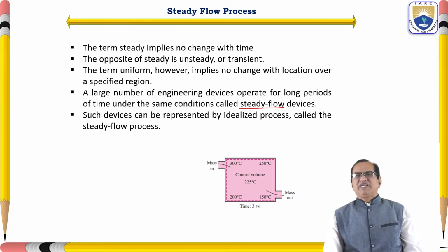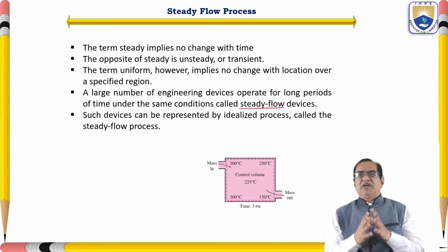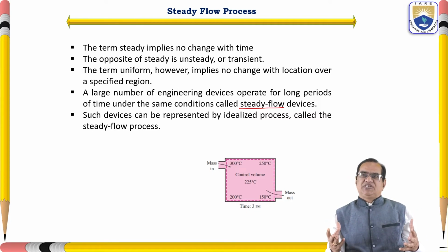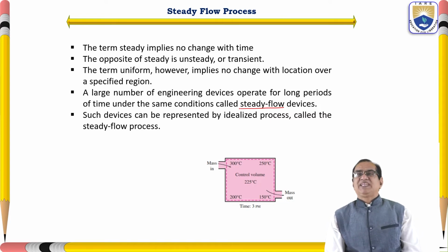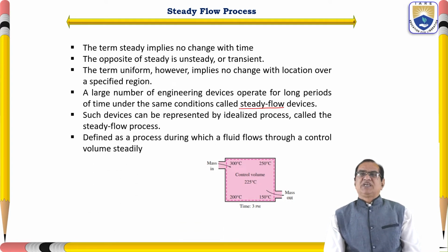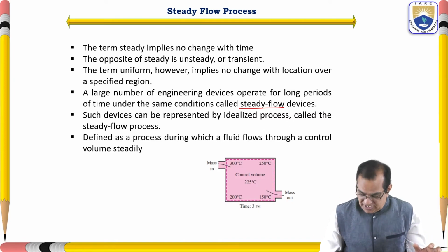Such devices can be represented by an idealized process called the steady flow process. The systems I just mentioned, like a heat engine, IC engine, piston engine, SI engine, CI engine, turbo engines, turboshaft, turboprop engine, your thermal power plant, your air conditioner, are all steady flow processes. A steady flow process is defined as a process during which a fluid flows through a control volume steadily.